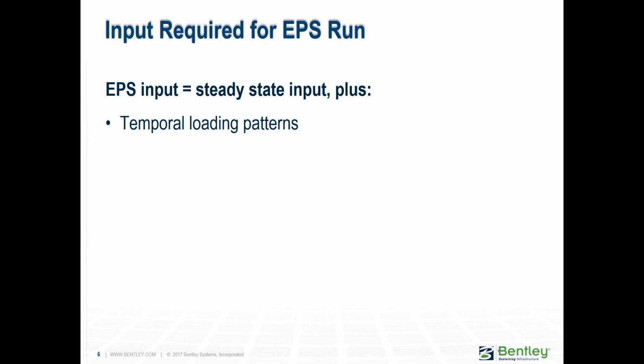X value at this manhole. But we weren't telling it if it happens all at once, or if it happens maybe nothing in the morning, and then all of a sudden, boom, we get 50, and then maybe at 6 p.m. we get another 20, or we haven't specified that, and we have to come up with that. And sometimes it isn't too easy to develop that, so you have to put a little bit of work into that.